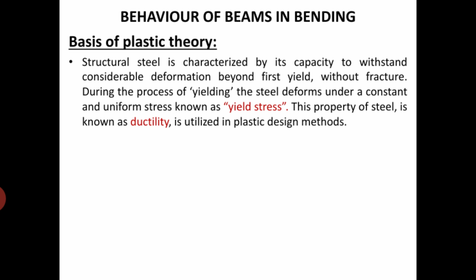As we know, the stress strain behavior of a mild steel when it is being tested in a UTM, we get the deformation as well as the behavior of that material under tension, and also the behavior of ductile materials as well as brittle materials. Since the mild steel behaves as a ductile material, we get a large deformation before its failure.